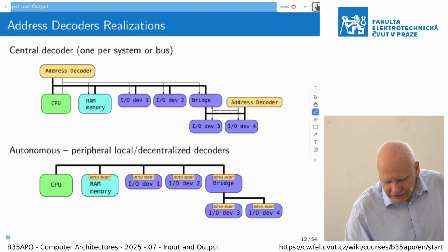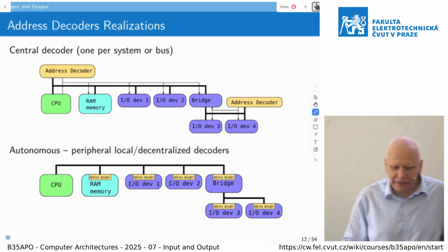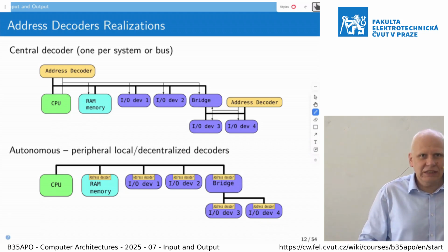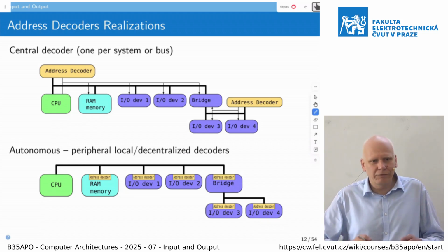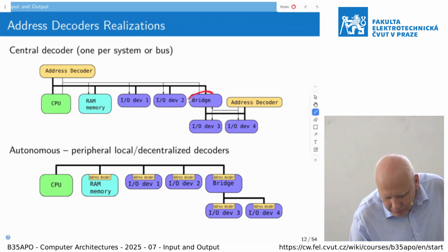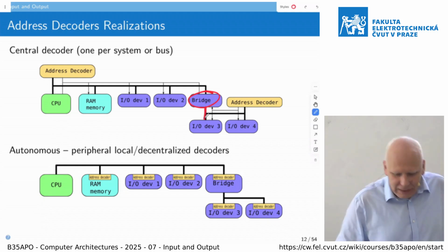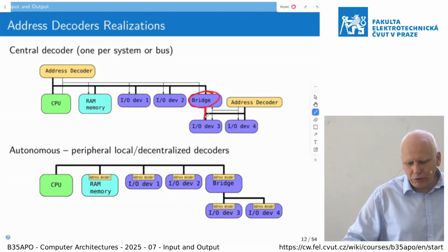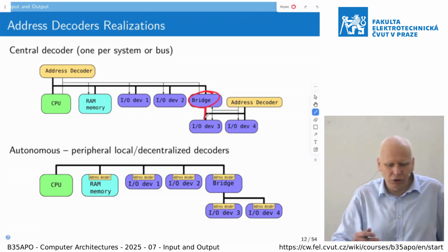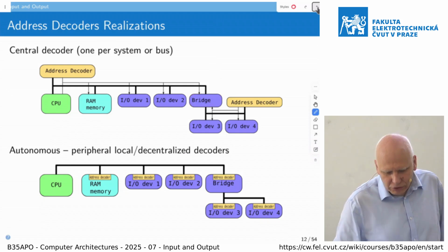Often this fast bus connects only the core components, and if you need to add more components, then there is a limited fan out on the signals on the bus. So usually you add a bridge, which can hide, again, the same type of bus below, or some other kind of slower bus for cheaper and not so fast peripherals.